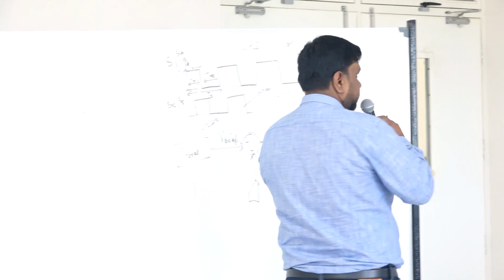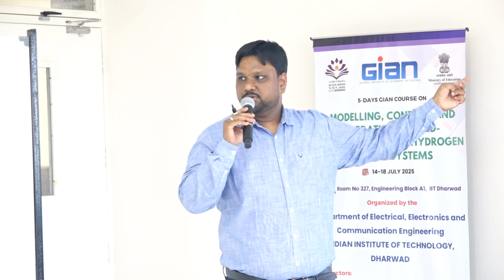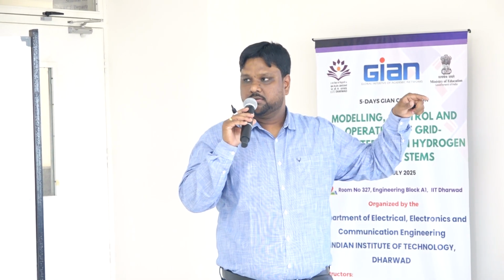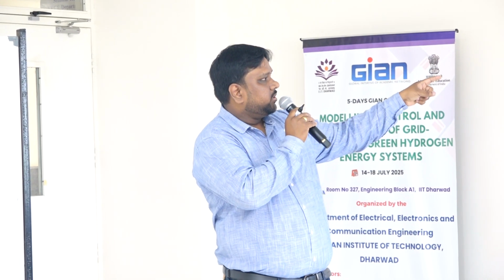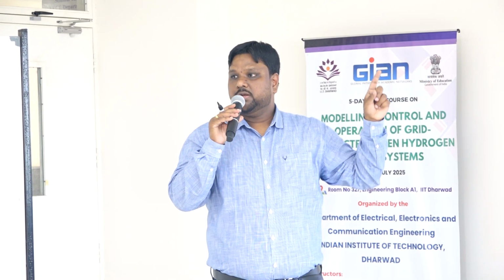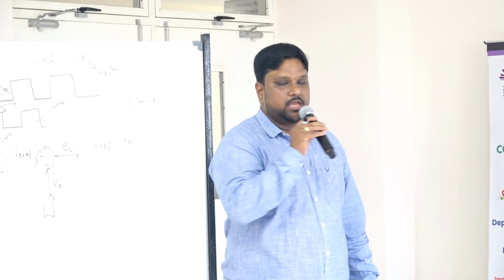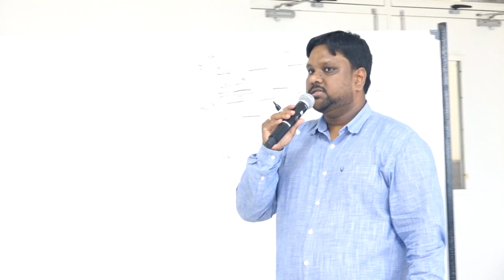Basically, the sliding surface consists of three terms. One is directly the error, then you add a constant times the integration of that error, then another tuning parameter, the absolute value of that error to the power lambda, and the signum of that error. Understood? So how many terms are there? One is EV, one is K1, K2, lambda. These three are your control parameters. You will play with these parameters to achieve a robust response, okay?